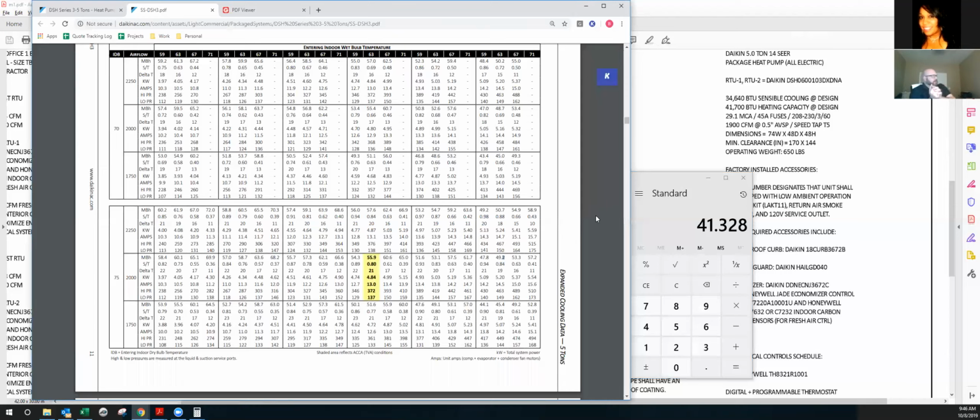And so you're going to put a lot more wear and tear on that unit. Bigger is not better in air conditioning. You want to size it to the heat load as close as you can, go over a little bit so you make sure you're covered, but if it's a 3.5-ton application, you don't want to put a 5-ton on it and think, oh, I'll be really comfortable.